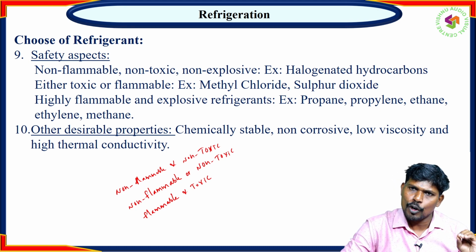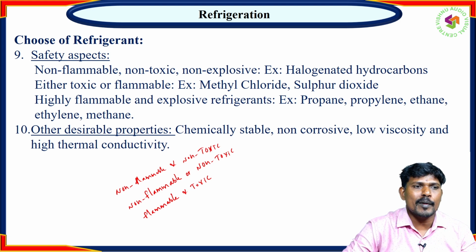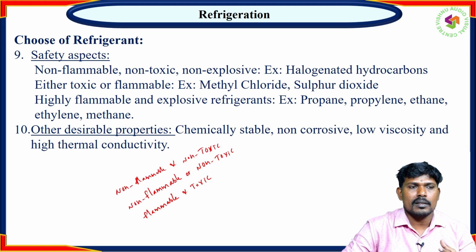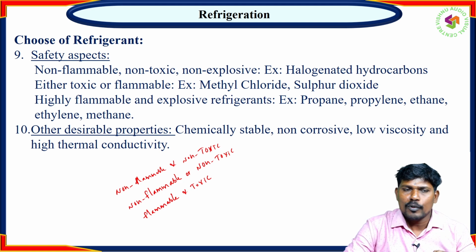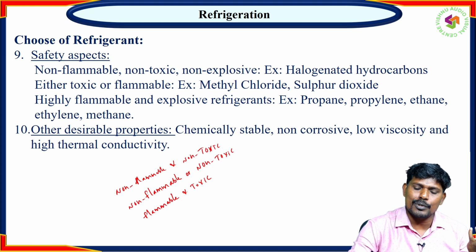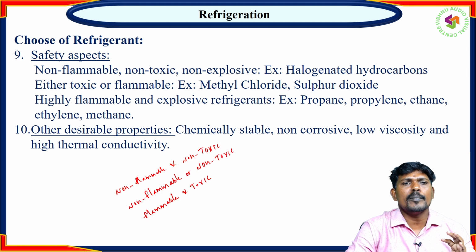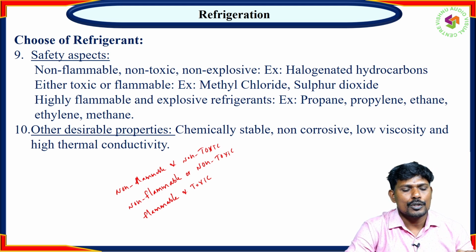Is it non-flammable and non-toxic? These are more preferable. Non-flammable or means either non-flammable or maybe it is non-flammable only, but it is toxic. Like that. Or flammable and toxic. So based on the circumstances, for example, in your system, there are no operating conditions that will cause an explosion. In that case, you can choose, for example, flammable but non-toxic. So based on circumstances, you can choose.